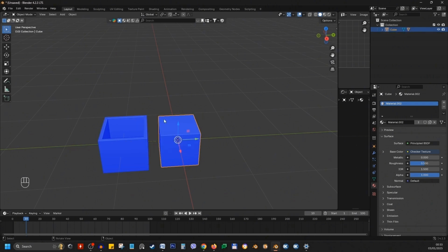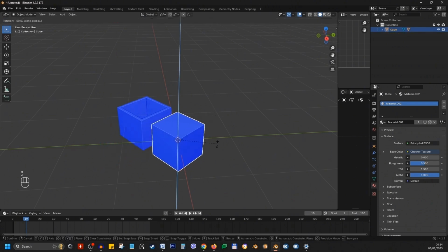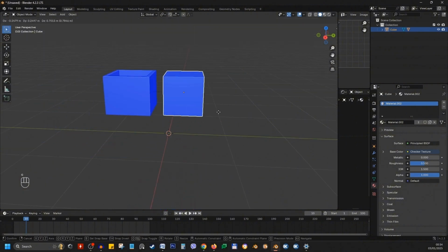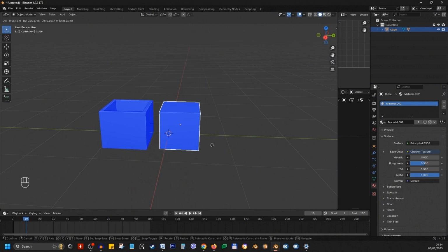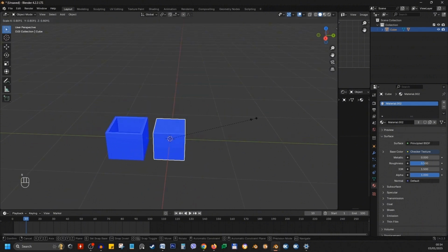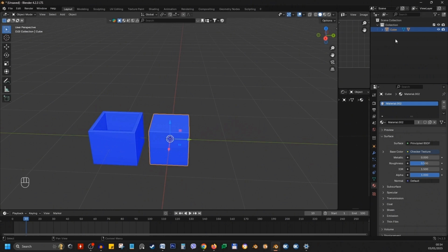So now by selecting this one and rotating, you can see I'm rotating both of them. G, the hollow cube follows the one in the center, whatever we do with it. Moving, rotating, but also scaling. One thing that happened is that in our outliner, now we see only one cube. Since we parented the hollow cube, it kind of went into the other one.